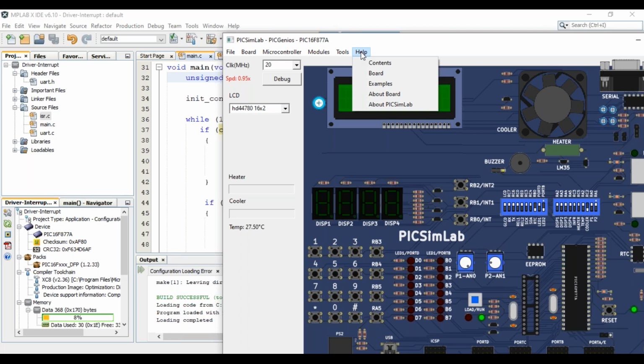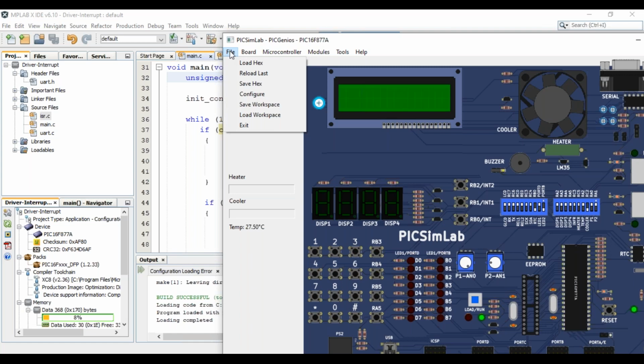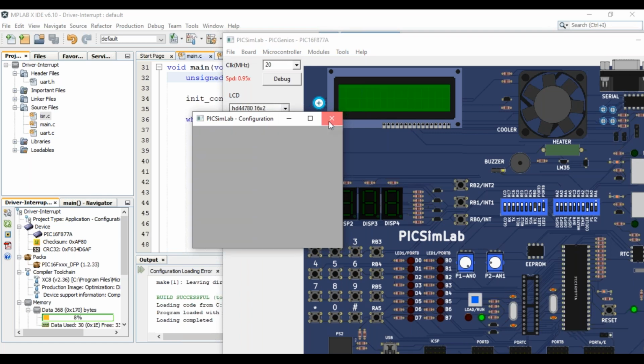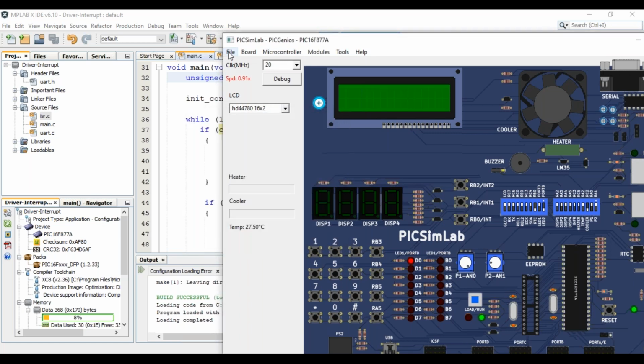So on this application, you don't have an option, but in fact, the earlier version had an option to choose 9600 here as well, but I don't have it. Anyways, you are setting it in your software itself. So you have informed your microcontroller to work with 9600. So your CuteCom should be working with 9600 being the baud rate.